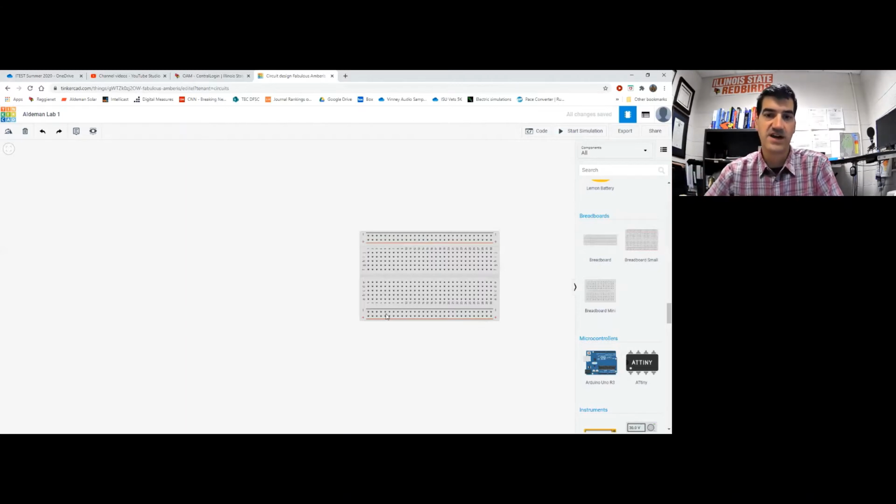They're connected horizontally. Right? In the middle here, it's the opposite. So here, pick one right here. Let's say that pin right there is connected with a little thin metal strip underneath the surface of the breadboard to that pin and all the other pins in this vertical row like this.